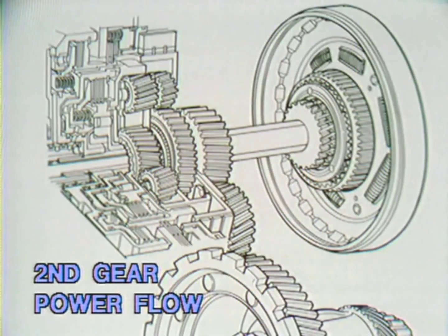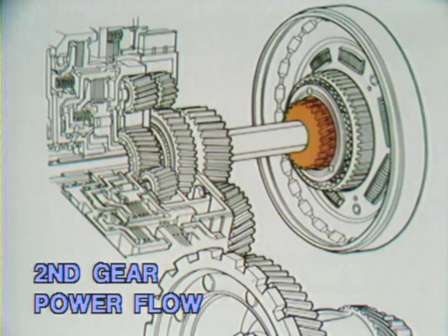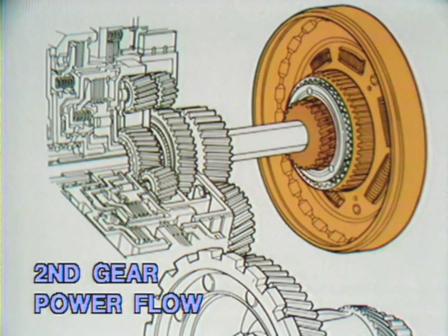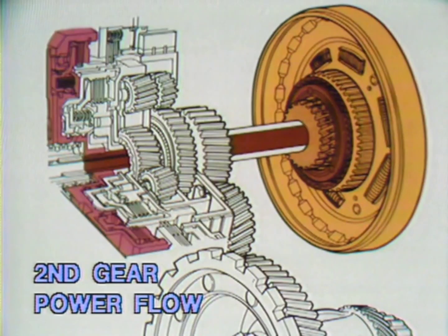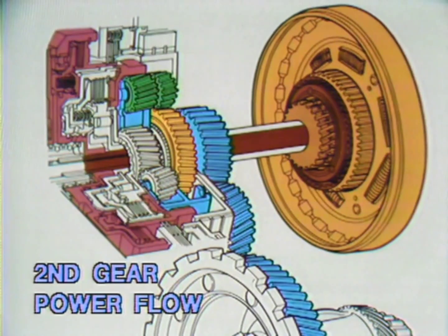Second gear power flow is hydraulic from the turbine to the splitter sun gear, and mechanical from the converter cover. They are combined in the splitter planetary unit. From the splitter planet carrier, 100% of the power flows to the intermediate shaft, through the intermediate clutch to the ring gear, to the long pinions which again walk around the sun gear, to the pinion carrier, and to the final drive gears.